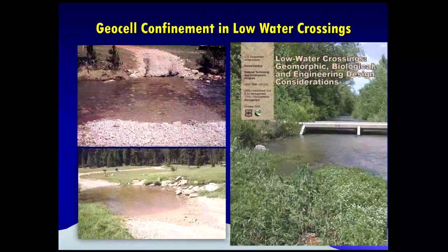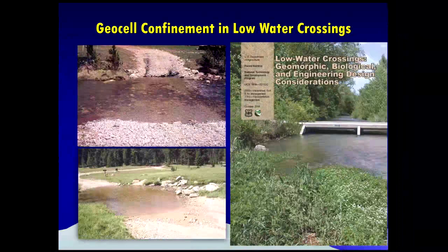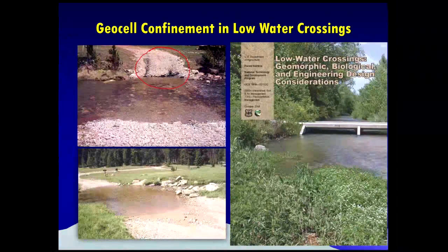Mostly for my rural roads, low volume roads are very unique in the rural areas where I don't have to cross major bridges or crossings. Wherever you want to make a temporary halt, you can see the geogrid is placed under the water and the aggregates are placed, and even with the water there, the mat is visible. So this will help us to move the traffic.